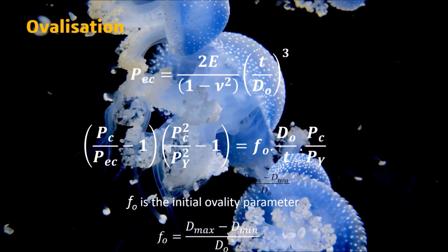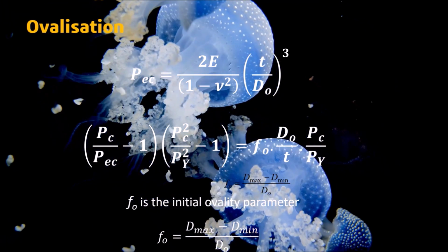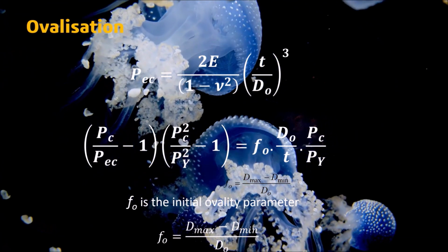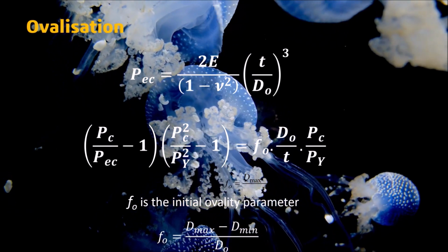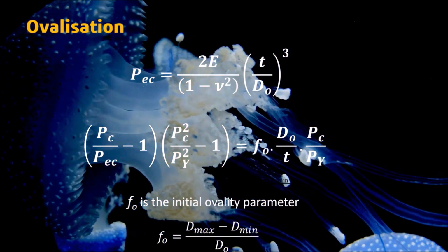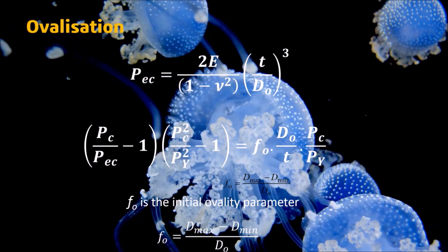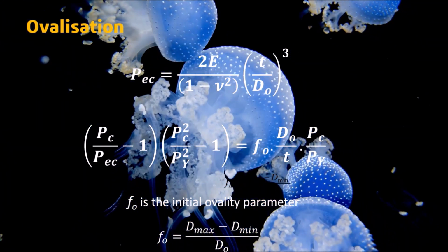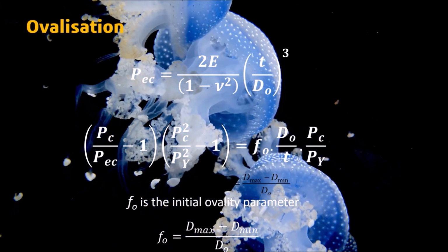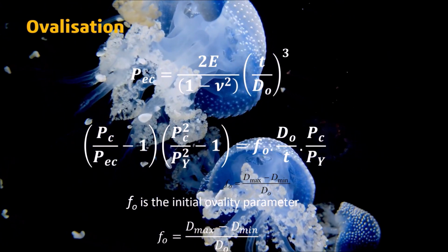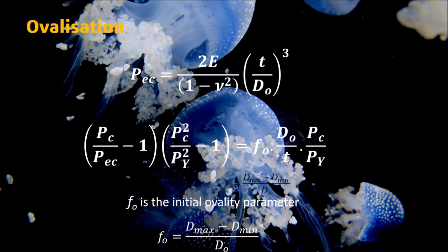These equations you can find in many standards or design codes such as DNV and British Standards PD8010. You should appreciate that this complex relationship only considers external pressure, but in reality a submersible or pipeline can have a combination of loading. This makes life very difficult to come up with relationships which account for the interaction of different loadings. There are some conservative equations available, but for complex geometries and loading, computational modeling is used as discussed in the previous part.